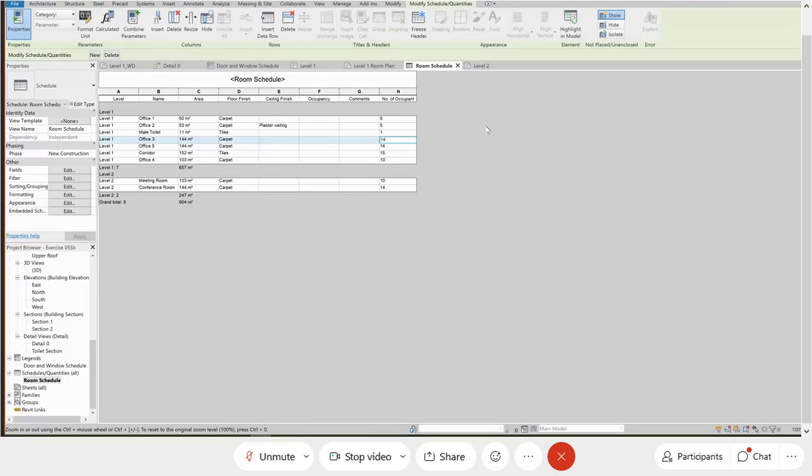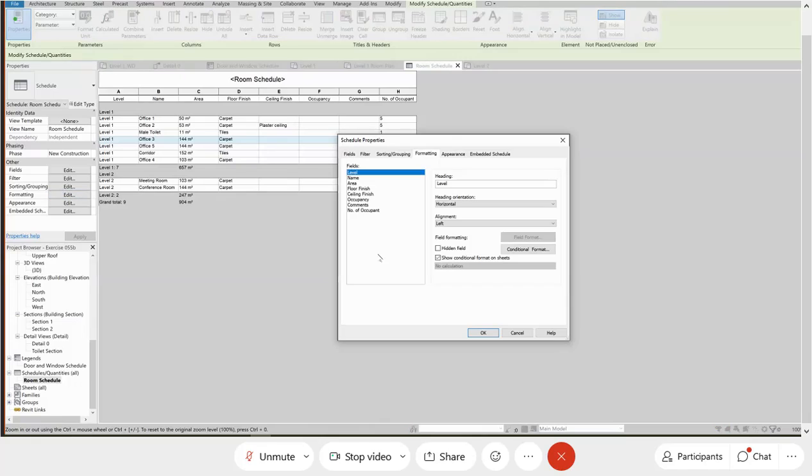In our BP submission, we need to calculate the percentage of this opening: 10% for lighting, 5% for ventilation minimum according to UBBL. So all these things you can just key into your Revit schedule and calculate automatically. Any question?